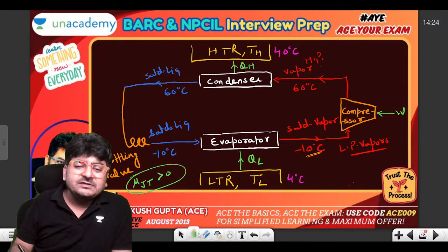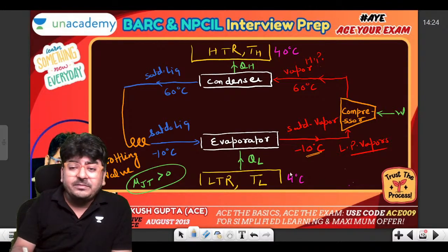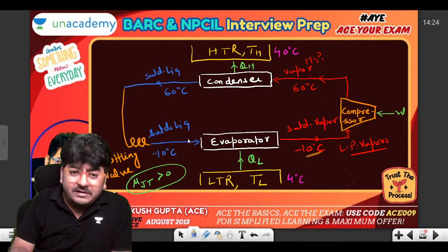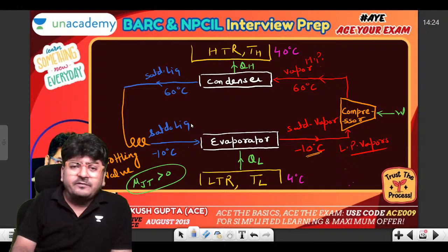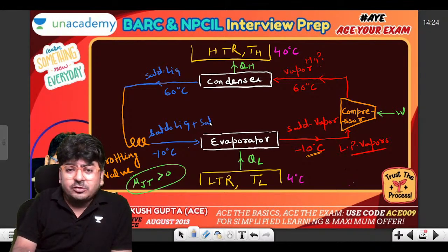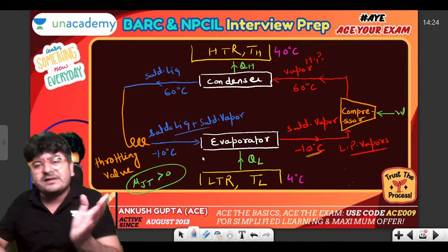And if temperature decreases, it is also possible that some of the liquid may get vaporized. So ultimately, in practical scenarios, along with the saturated liquid, we might have some saturated vapors also. So a mixture of liquid and vapors enters the evaporator.